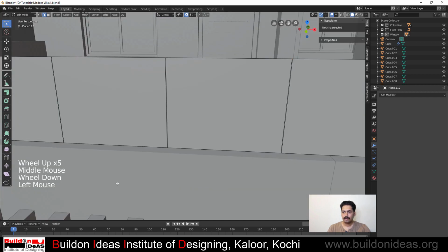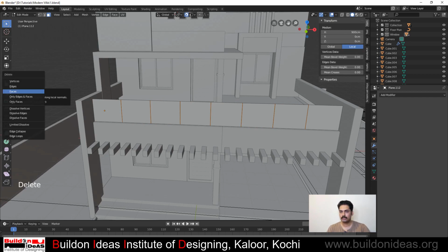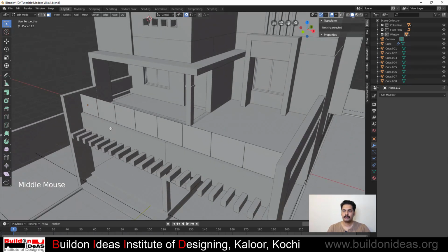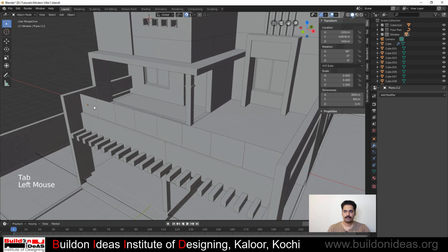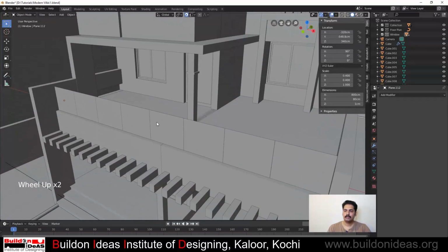Okay, now I just select all these faces, and Control I gives an invert, and then I delete the faces, so there's a gap in between. Now extrude, say 1 centimeter. Now I have the glass ready.